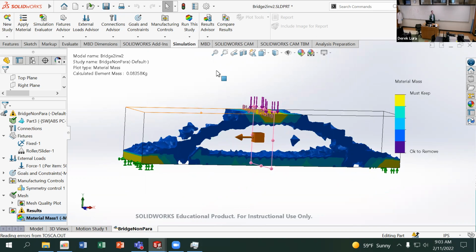And the problem with this is when the stress distributions are too small, basically the variance in stress isn't sufficiently large, it basically gets rid of everything. So the video I have that I'll post on Canvas from this morning is I did an axial load. And then if you look at the results, it says you can have the 2 plates with nothing in the middle, right? Which is obviously wrong, right?